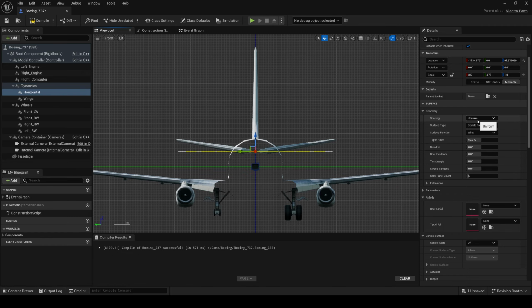So, oh no, before I get there, we're still using uniform. It's double pane, 2 sides, but this is now a stabilizer. If I then start to increase the dihedral to match the shape of the mesh I have here, so this is I think 7.5 degrees now. Nah, 7.8 degrees. 8 degrees, okay, fine. We'll set it at 8.